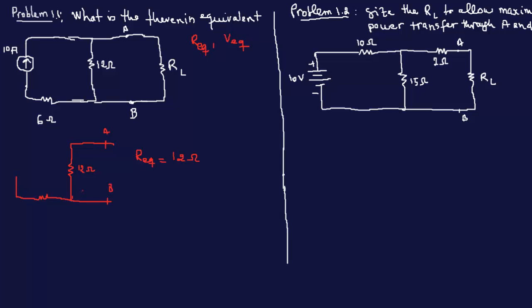All right. So now to find the voltage equivalent, we have voltage is equal to what? Voltage is IR. I is the current source that was already given, because when you're finding the voltage equivalent, you have to put the source back. But when you are finding the R equivalent, you have to open circuit the current source. And if that was a voltage source, we have to short circuit it, like the problem on the right side. But we're gonna get there in a little bit.